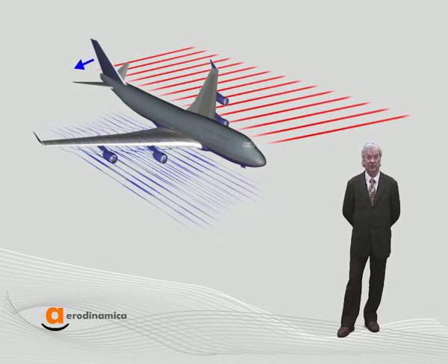Of course, a stable airplane is more difficult to fly, as it does not respond to all commands of the pilot. Why? Well, the commands of the pilot are like disturbances for the airplane. If the airplane is very stable, it will tend to nullify the pilot action. A funny piece of information: some military airplanes that require a high maneuverability have low stability margins or are even unstable.